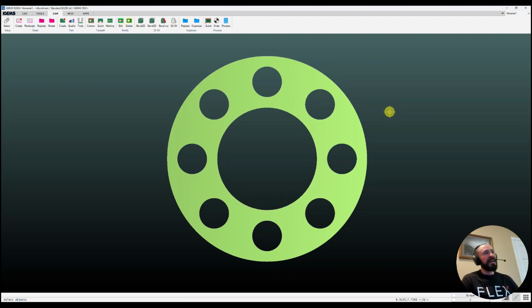So what you should see now is your CAD geometry gets colored in into a solid part. If it does not get colored in, or it's not what you expect your part to look like, you probably have some error with your CAD, be it an open line segment or a dirty import that you'll need to clean up and fix before you can progress to this next step.